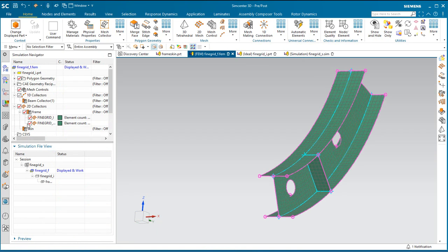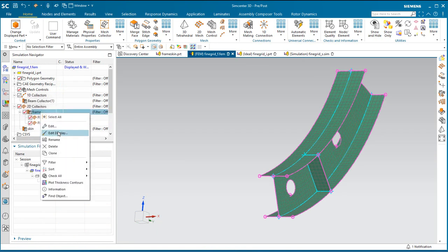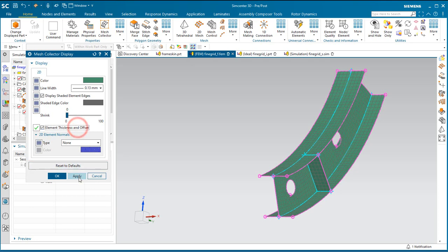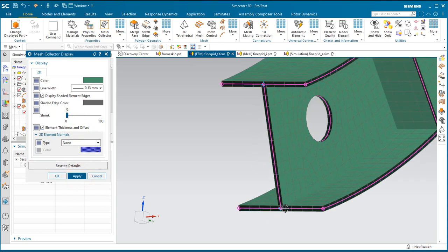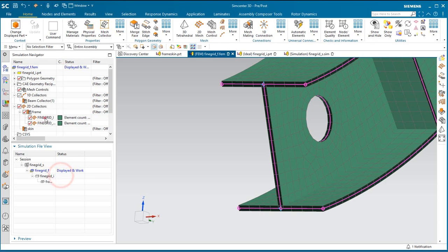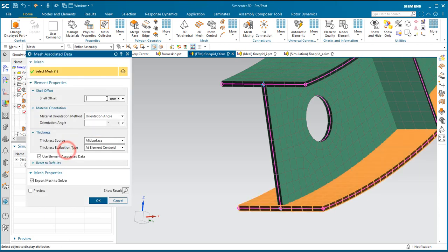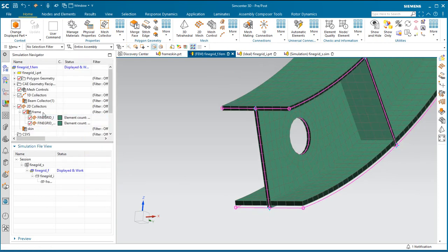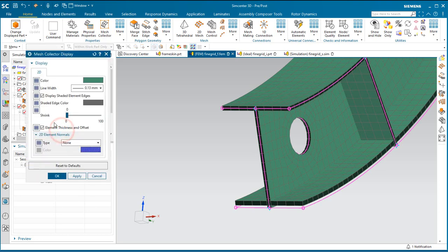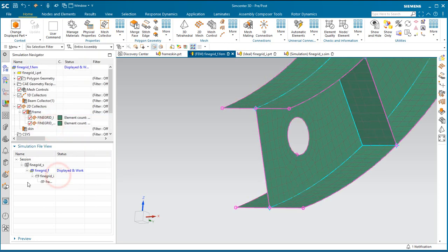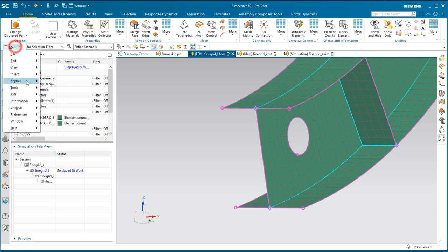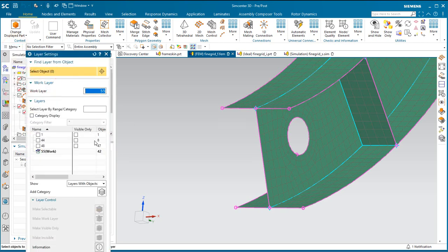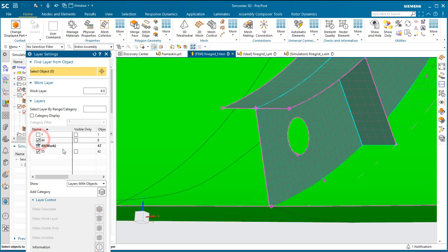And the reason why I've put it into two meshes is because if we take a look at the offset and thickness of our shell mesh, that bottom flange really should be offset by the thickness of the skin so that it's at the correct location. So we can do that if it's a separate mesh. Alright, so that looks good. Let's go ahead and mesh the skin next in the breakout region.